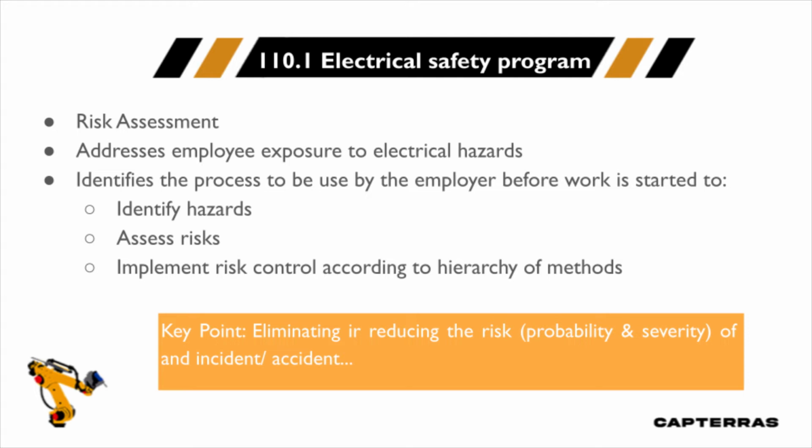As I still go in the field and work today, I still wear the arc flash protective gear. So we're not just talking theoretically here. Every time I look at a piece of electrical switchgear or a motor control center or something like this, I'm making an assessment. Is this equipment properly maintained? What does the installation look like? How old is the installation? Are there vent holes in the covers?